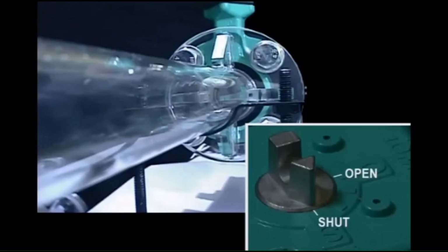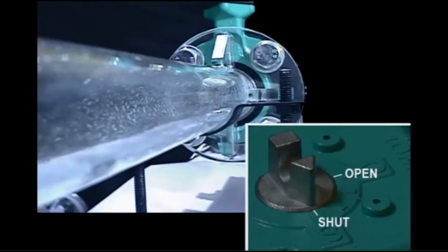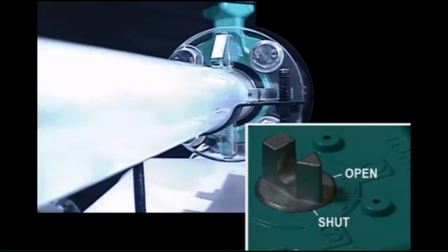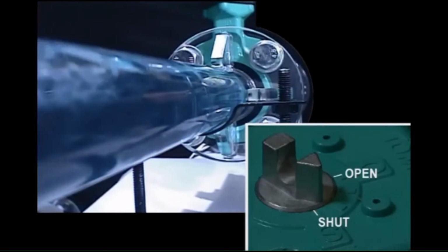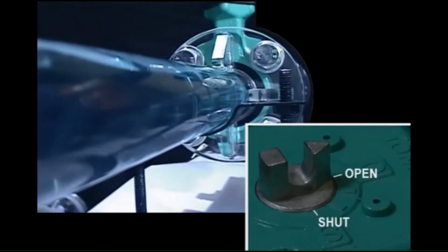With butterfly valves, since flow is not proportional to valve opening, remember that a large quantity of water may flow even if the valve opening is small. In short, open valves gradually by inching, stop when slightly open, and observe the state of things for a while. For valve closing, also do it gradually by inching. We can go so far as to say that most of the troubles associated with ballast operations can be avoided unless you open and close valves abruptly.